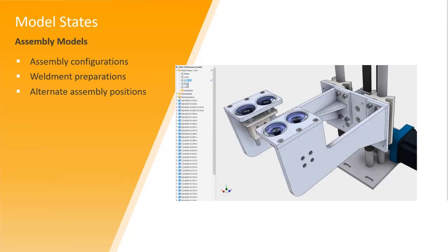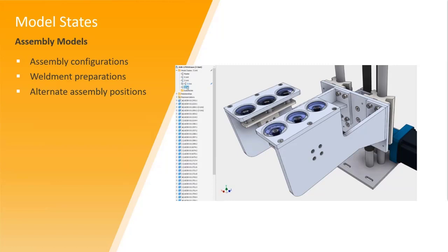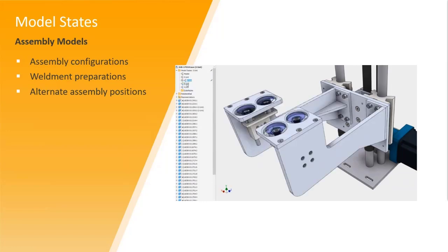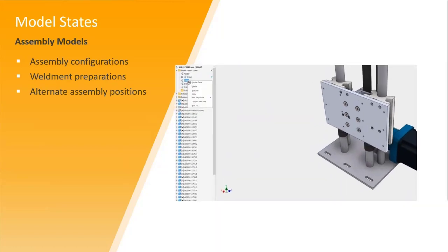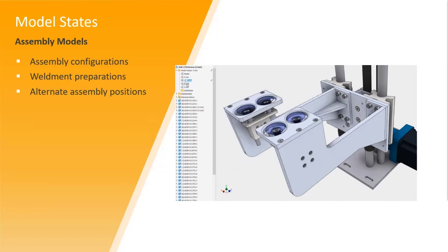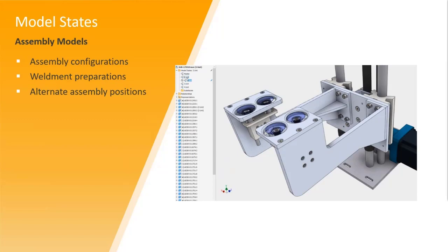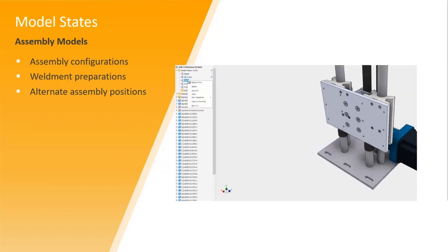Autodesk Inventor 2022 introduced new functionality to help you create multiple representations of your design inside one part file. Model state can be used in a part model to capture your design intent, showing flexible components, families of parts, or a simplified version of your design without creating an additional file. Each model state has its own iProperties, allowing you to create families or variations of parts with unique metadata such as material or stock number.